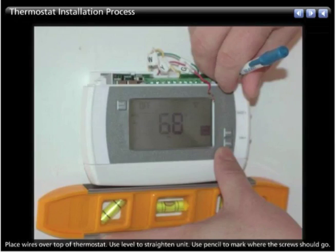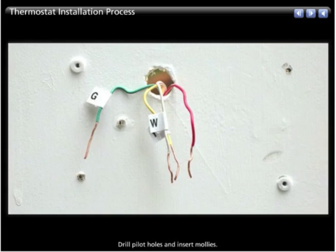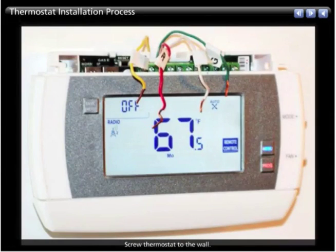Next, place the wires over top of the thermostat. Use your level to straighten the unit. Then, take your pencil and mark where the screws should go. Now, drill pilot holes and insert the mollies. Now, screw the thermostat into the wall.